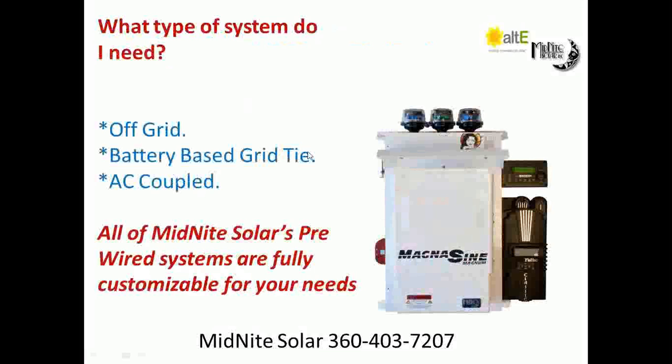There will be no power in the house because there are no batteries. So in order to have backup power when the grid is down, you have to have the batteries in the system, which now puts you into a battery-based grid tie system. The other two common types of systems that you'll hear referred to are off-grid, so there's no utility grid there at all. You want to be your own utility grid, you'll do an off-grid system, and with that you'll probably have a generator input to it for backup if the sun doesn't shine, for instance.